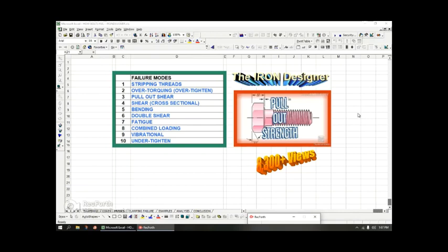You could also have fatigue loading, which means that you're applying axial stress and removing it, applying axial stress and removing it, applying it again and removing it. So using the bolt almost like a rubber band. Even though the bolt is fully clamped and fully torqued to the specifications, you could apply additional axial fatigue to the bolt. You could do combination loadings, as I've talked about before. In fatigue, you can also have reverse and repeated loads.